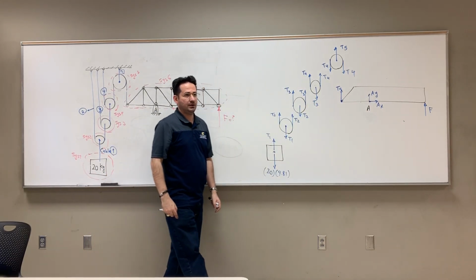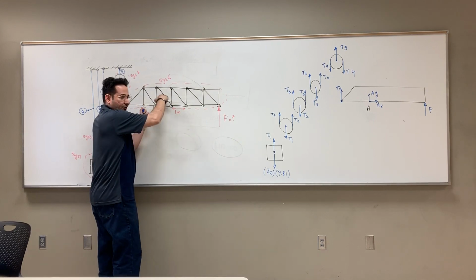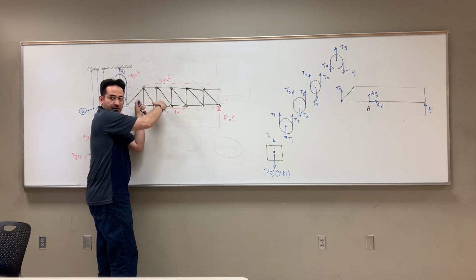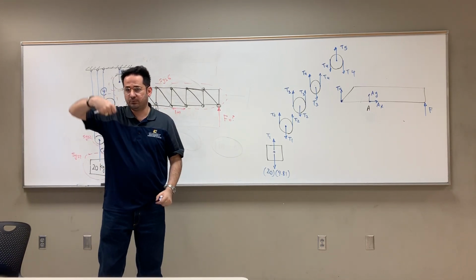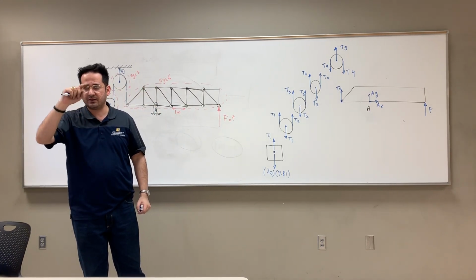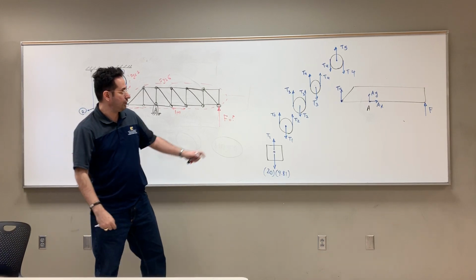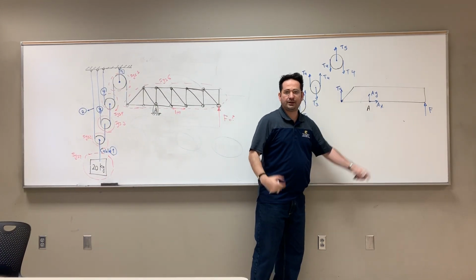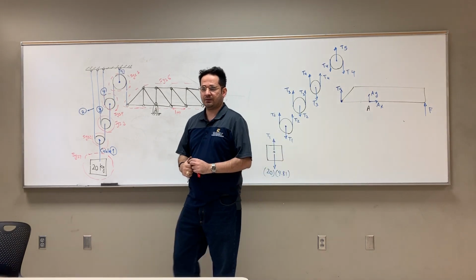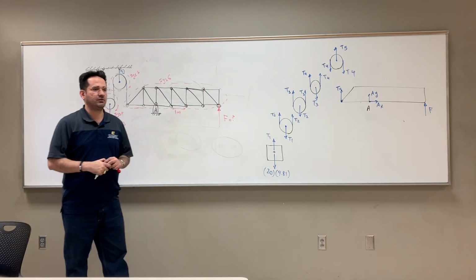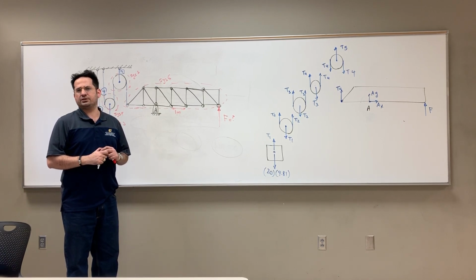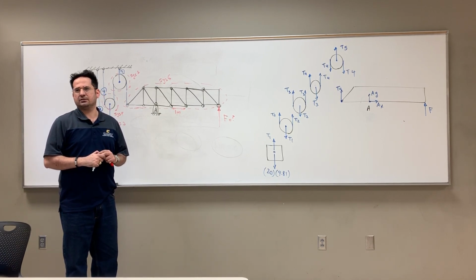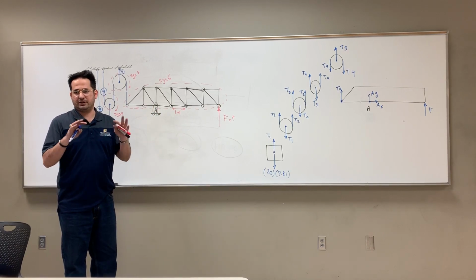That's unknown. Now you say, can I rotate it like this? Can I rotate it about this point? Yeah. You don't need to put so much force in it to do that. You can easily rotate it. So there is no counter moment coming from the reaction there. This is the 2 pages I said, study the free body diagram 160 and 161. One of those 2 pages. This comes from the way you isolate the system.